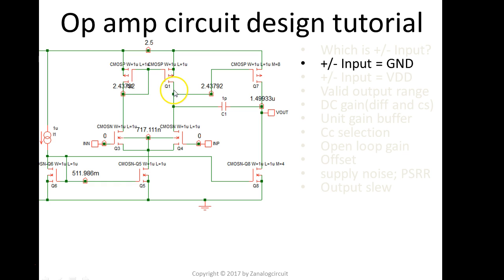In a simulator, everything is perfect. There's no mismatch between these two guys. There's very little leakage, so that's the reason everything is balanced. The voltage here equals the voltage here. But in reality, you just don't know which, this Q1 device or Q4, both of them are off, right? But you don't know whose leakage is higher. So technically you have no idea about this voltage.